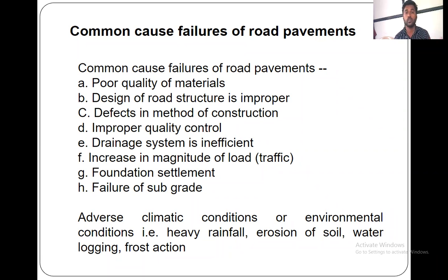Suppose whatever the water quality, the WC ratio, water cement ratio, because in construction you might have observed they will not at all maintain the water cement ratio. They simply put the pipe of water into the concrete mixing where they batch.